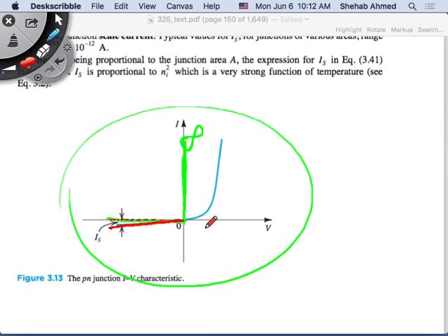But current intensity depends on the concentration of holes and electrons. Yeah, that's the next stage. Next stage is now, okay, fine. Because the concentration of holes and electrons is different and it's actually exponential, which, I mean, the diffusion concentration, right? The concentration of the majority carriers. The majority carriers are the ones that give me diffusion, right? So since the concentration of the majority carriers is exponential, and they are the ones that create this diffusion current, hence the diffusion current is increasing exponentially, right?